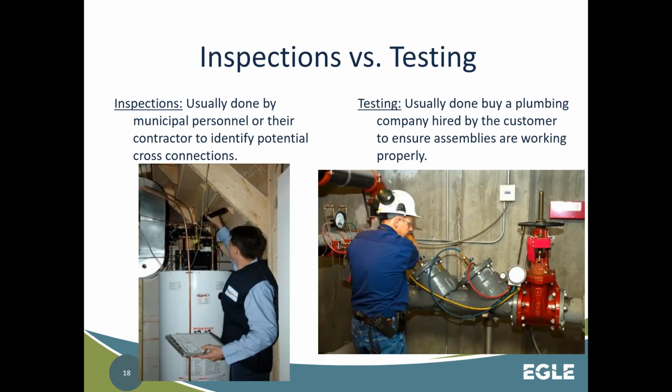All right. So now testing. Back before all this stuff, before rule changes, in order to test assemblies, you needed to be a licensed plumber. Okay, that has changed. There is a certification offered by ASSE, okay, you can become a certified backflow tester, and it's ASSE 5110 certification. You can find licensed testers on their website. Go to ASSE's website and look up licensed testers for your assemblies.